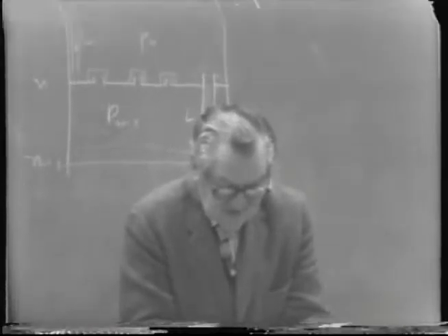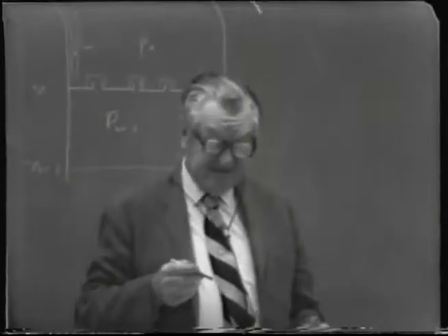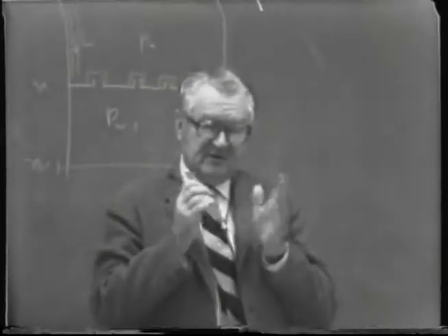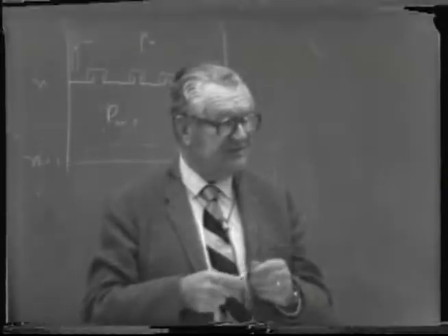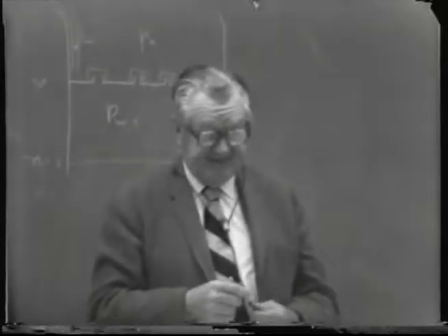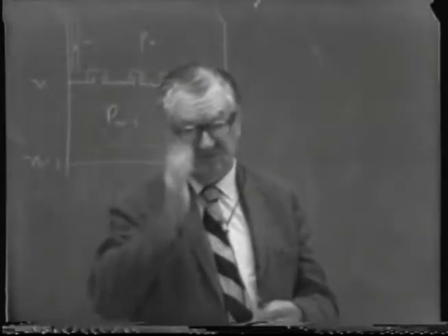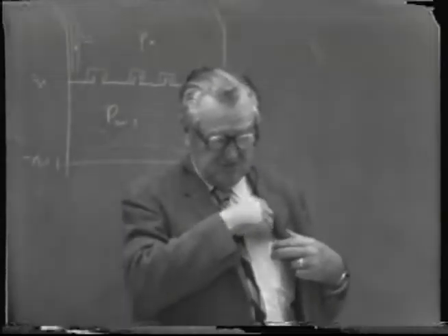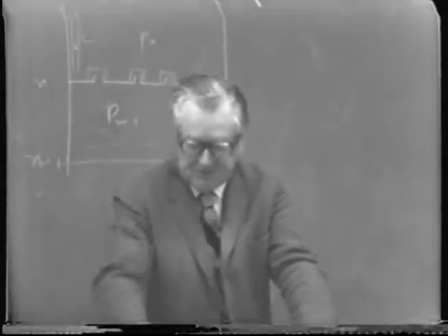It was a continuous column, much in the same vein as we now use, but the idea was that in order to get all the alcohol out of pumice, they would slurry the pumice in a hammer mill disintegrator and be able to pump the whole mass through the column. That was possible, and there may be a few plants that still use this, but most of them have discontinued its use.